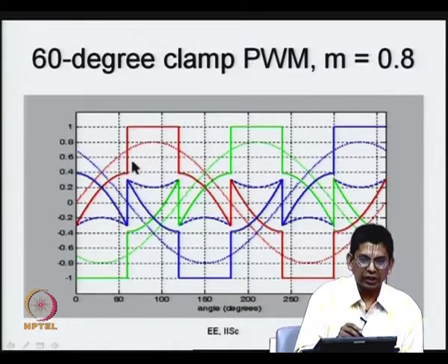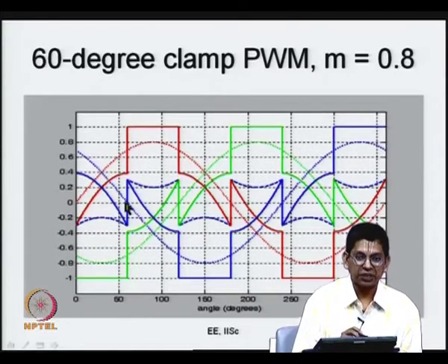So, whenever the R phase current is going through 0, the phase is not switching, and switching energy lost is proportional to the current it is being switching. So, the phase is keeping quiet, it is not switching when the current is going high, and therefore, there is a substantial reduction there now.